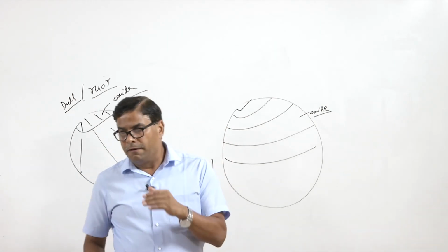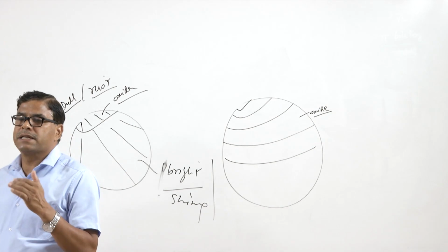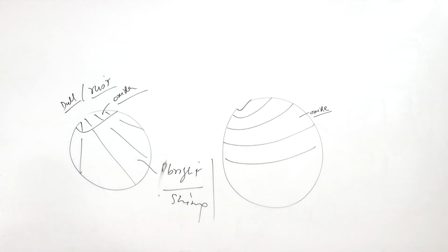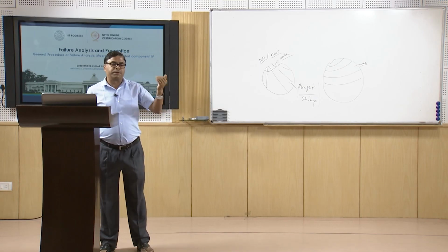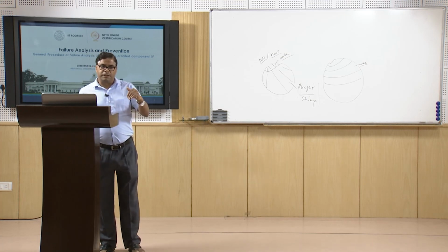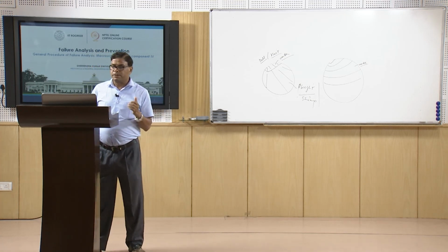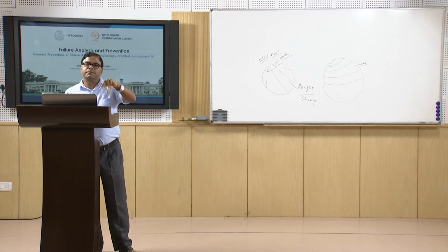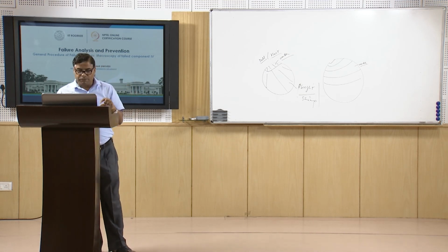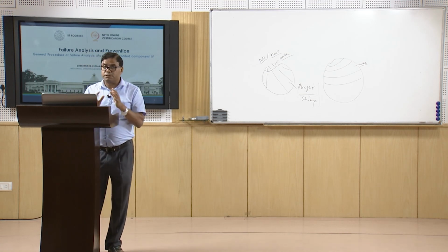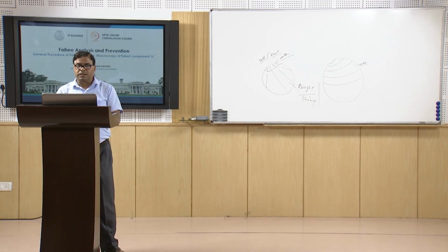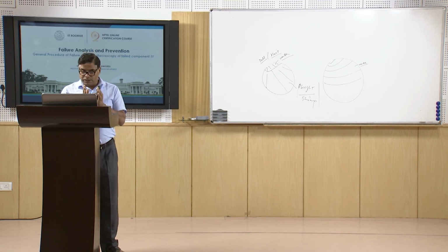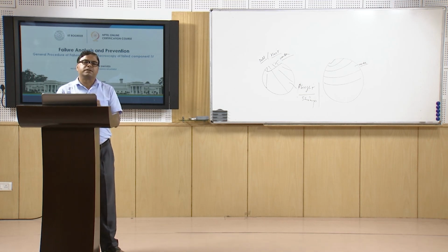Sometimes measurement of the oxide layer thickness helps to estimate the period for which the surface was exposed to a particular kind of condition. Once we know the thickness, then using the oxidation kinetics of that metal, we can determine for how long this surface has been exposed to the environmental conditions. So, we can also see if there is a surface having the oxides.